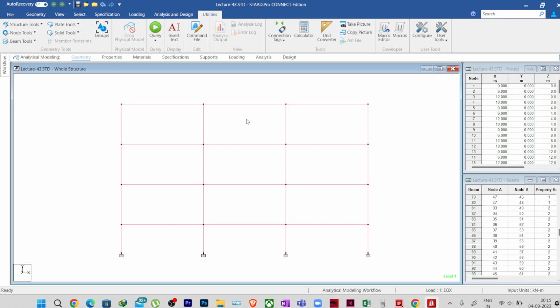So here, if I want to see the start and end of the beam, you can just directly go to the beam and you can see it. The green end is my start and the blue end is my end of the beam, correct? The similar thing we can see by pressing Shift E, and it will give us a view of the start and end of the beam. We all know that green is start and blue is the end of the beam by default. You can change it obviously, but as the default color, these are actually given.